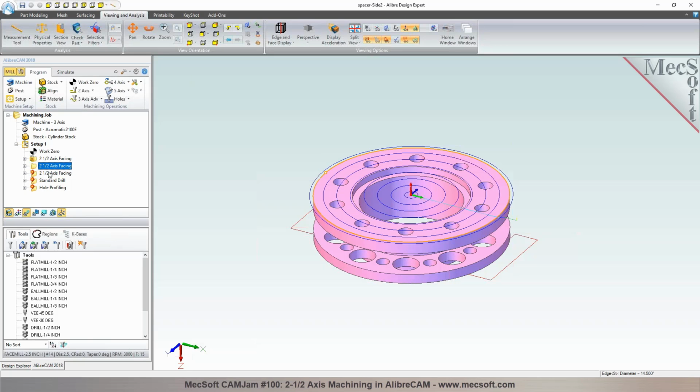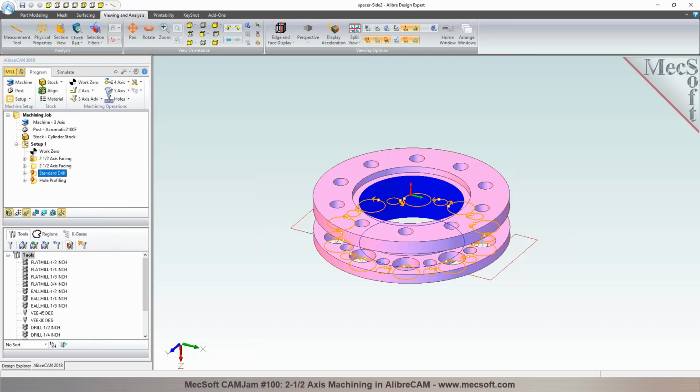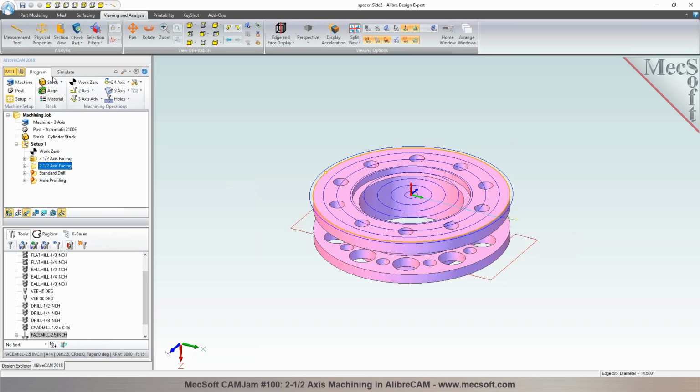So in this particular step, we just did a facing operation in here. Now to cut the step in here, is the hole already bored in the material that you're going to be cutting, or do you need to bore the hole in here? The hole's already in it. Already in there. So you just need to do a profile cut to clean up the step in here.